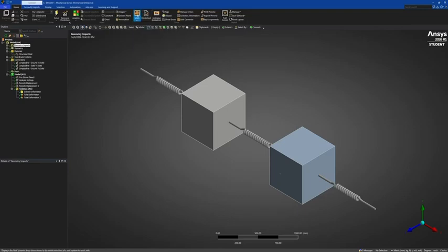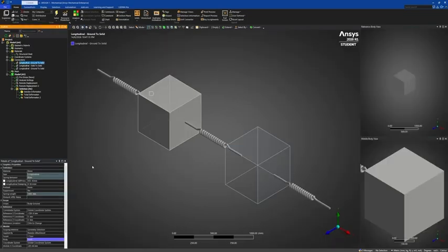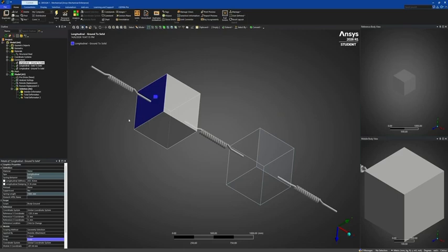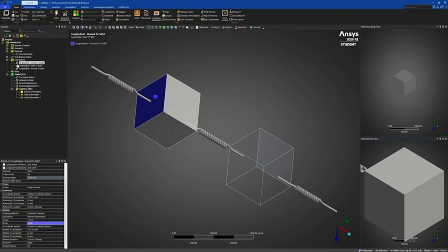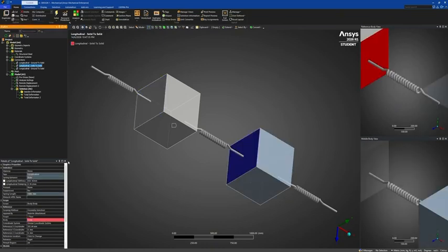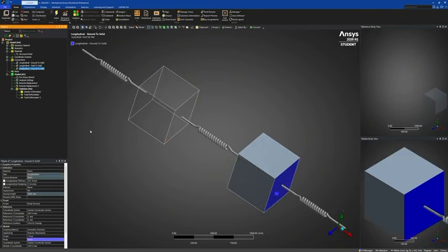In the model, make sure we choose the units correctly. First we set the material to structural steel. Next we set the spring connection, which is K1. We set it to body to ground, which is 450 Newton per millimeter. For K2 body to body, which is 650 Newton per millimeter, and for K3 body to ground, 250 Newton per millimeter.